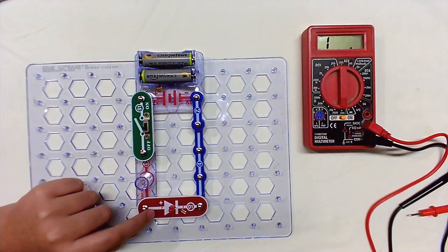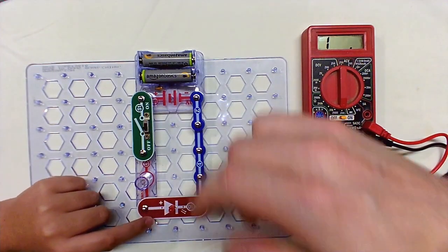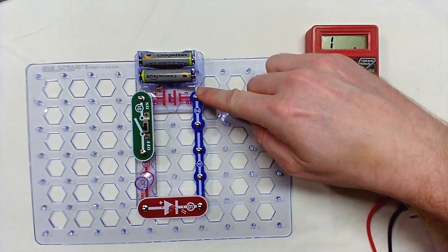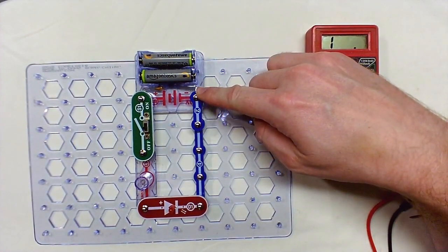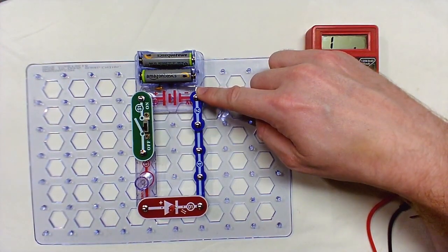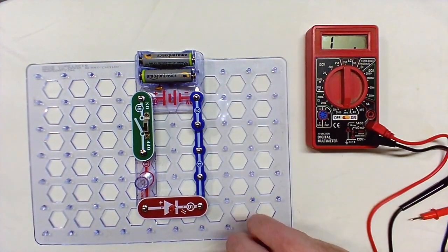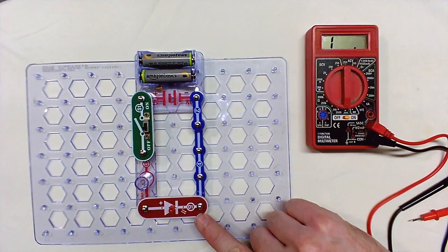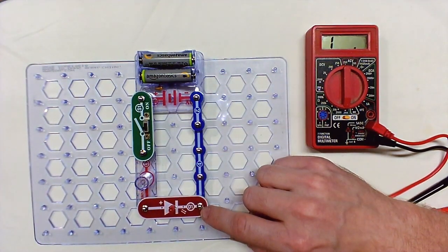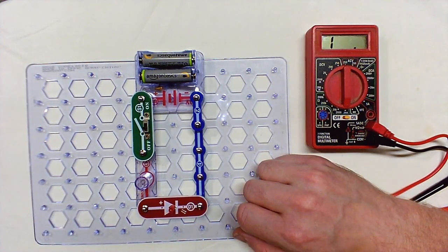Do you remember how we said that in a series circuit, throughout the whole circuit the amperage should be the same, right? Yeah. But what did we say about the voltage? The voltage changes. So the LED is going to reduce the voltage, and so is this. They're both going to reduce the voltage a little bit. So it's not enough for the lamp to light.